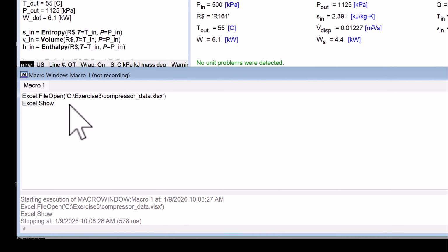So first thing I got to do here is an Excel.copy, and Excel.copy requires the range, and so for this particular case, when I'm just doing one data point, the range would be C6 colon H6. You notice the range is a string. That becomes important here when we start to manipulate this string to try to get all of the data points one at a time. But for now, it's just that string.